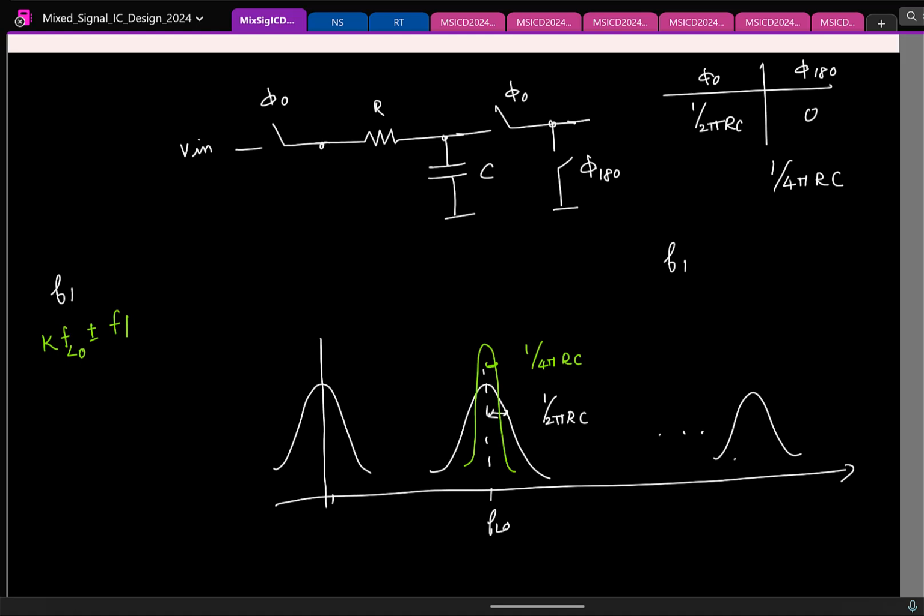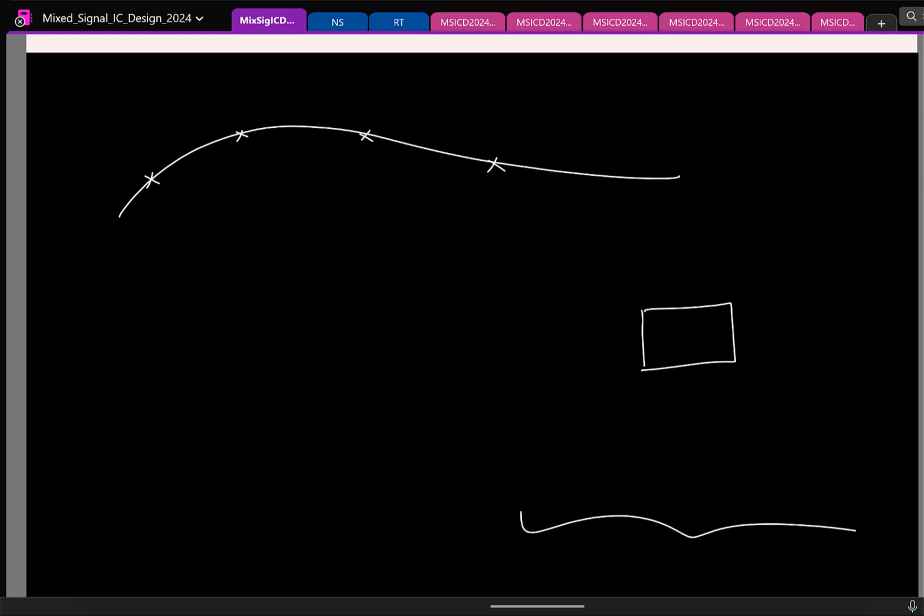So that begs the question: is it possible for me to cheat by having only a circuit, let us say, that samples at FLO, but to the outside world I should make it look like we are sampling at 2 FLO. So basically I want to also sample these points. As of now I have one circuit. I am giving a clock phi of t at FLO. That is basically taking these cross samples. But let us say I also want to take these points.